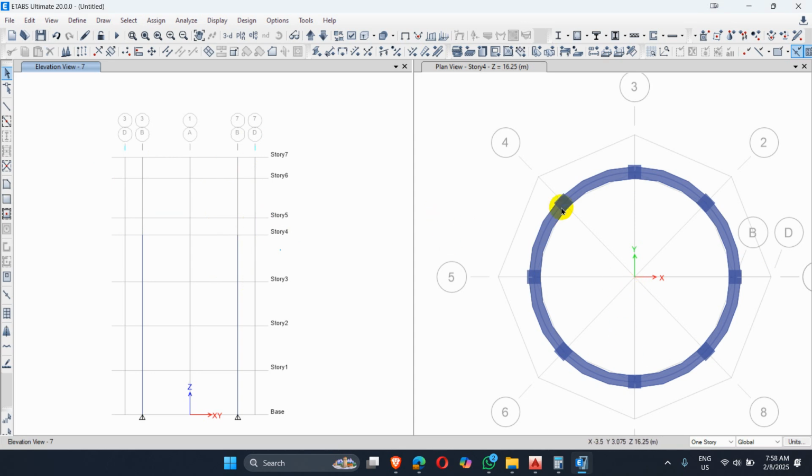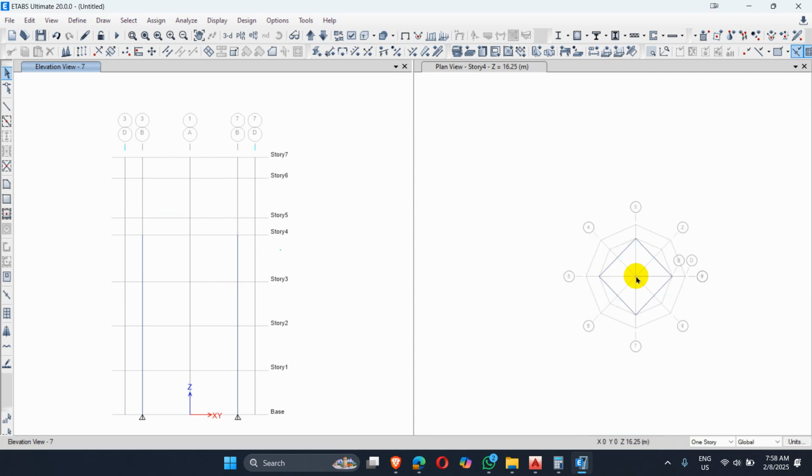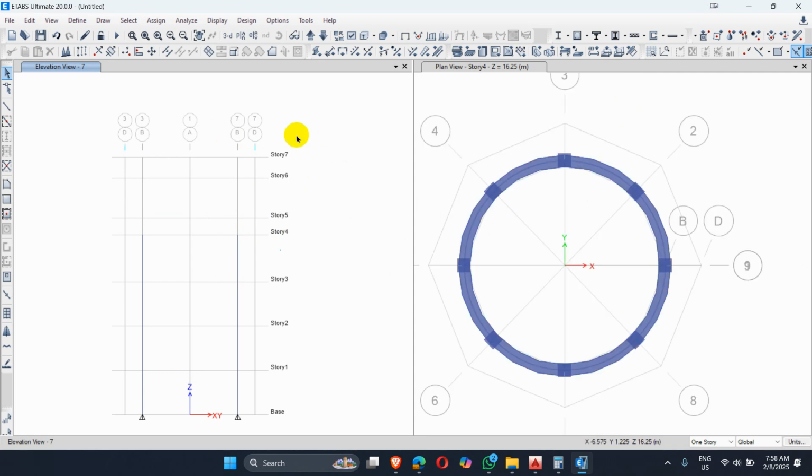So here I am going for elevation 33 and 77, or I can choose any elevation 55 or 99. For now I go for elevation 33 to 77, so that I can divide this distance, which is 4500 mm.